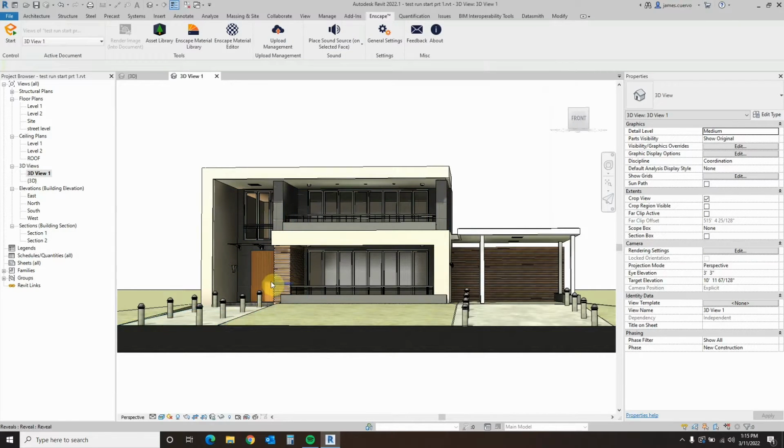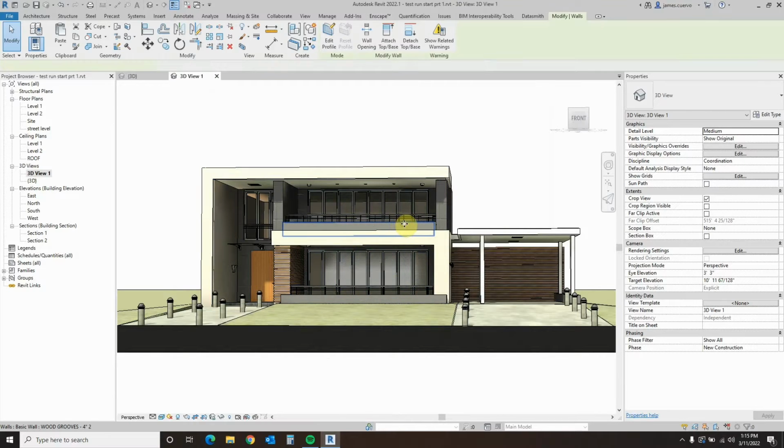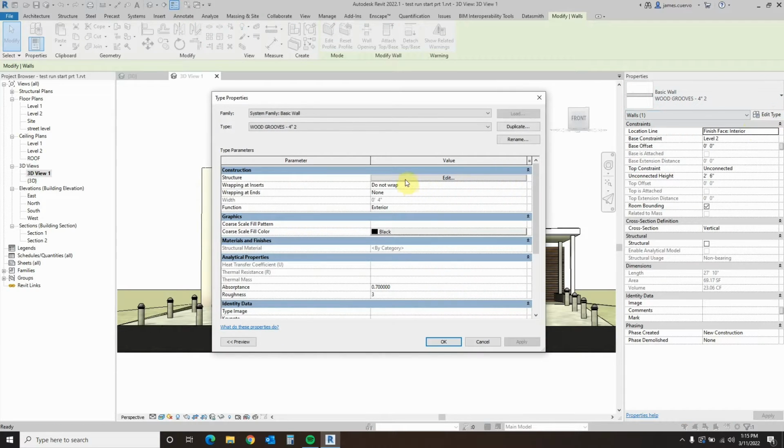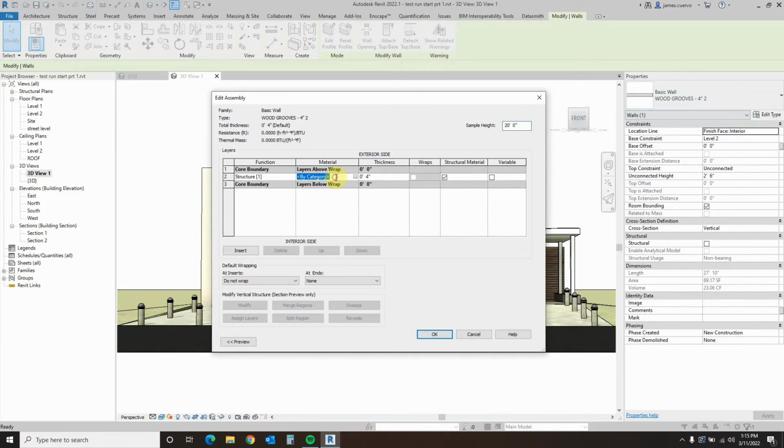Now we need the same material, but rather than using it in a vertical, we're going to use it as a horizontal at this wall. And this wall's here, and these little walls right here, okay? So what we'll do is then we'll go back to the wall here and select the wall. This has already been defined as the wood with grooves. We'll say edit type. Okay, then we'll come over here to the edit type again and select here.